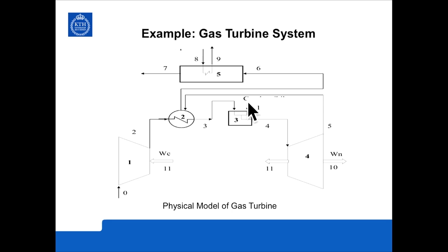It makes use of only one stream of external fuel, which is the natural gas flow number C. So we have air compressor 1, air preheater 2, a combustor 3 using natural gas, a gas turbine expander number 4, and a heat recovery steam generator number 5 producing a steam flow number 9. The 7 is the exhaust released by the chimney of the gas turbine to the atmosphere.